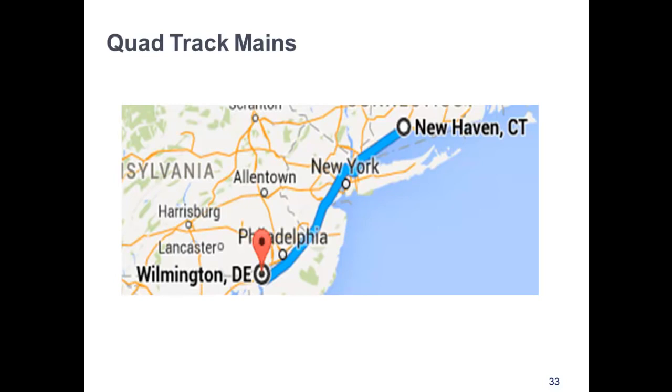And as we know, the Northeast Corridor from Boston to Washington sees about 2,000 trains per day, including the Acela, Amtrak regionals, the commuter trains, and about 65 freights. And there's 450 trains per day on 2 tracks, 1 per tunnel, right under the Hudson River. So with the quad track, how does that operate, Dick? Well, typically with a 4-track railroad, the middle tracks are for high-speed trains or zone expresses. The outside tracks are commuter rail and freight.